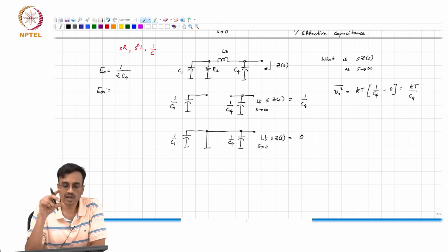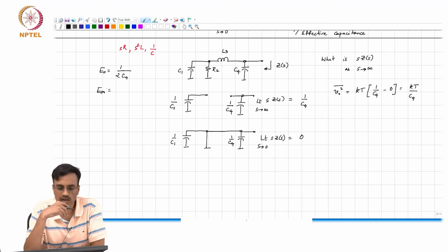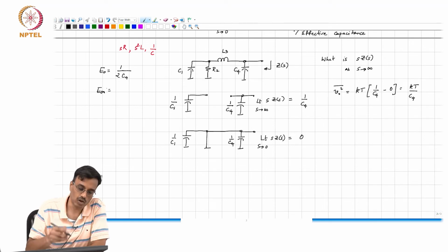There is some initial voltage on the capacitor C4 as t tends to infinity. Well, the inductors become short circuits and there must be no current flowing through R2, that is what will happen at t equal to infinity, and therefore, it is very apparent that both C1, L3 and C4 are all discharged, right, or disfluxed, okay, and therefore E infinity is, what is E infinity? 0.